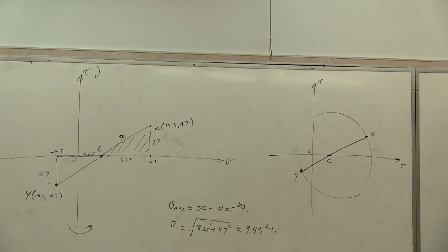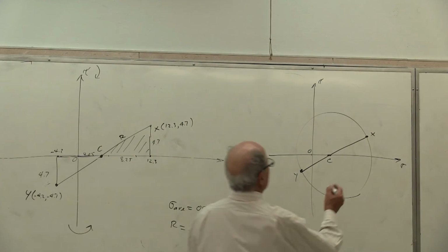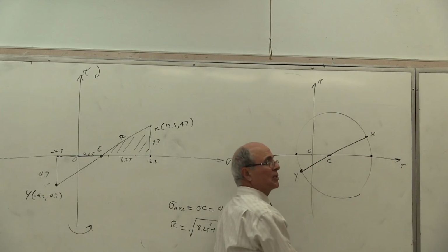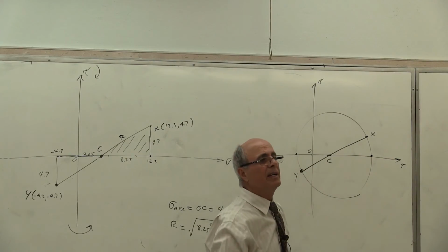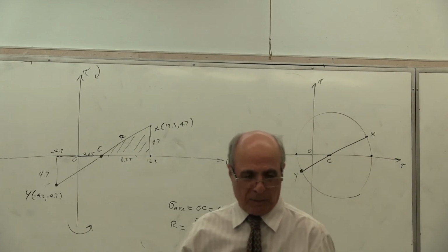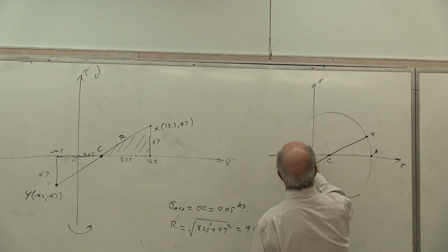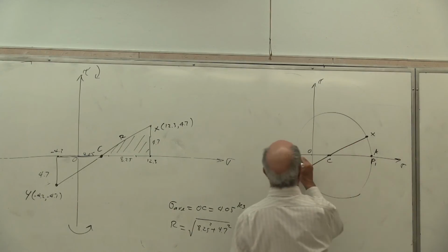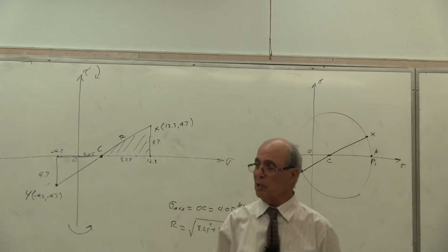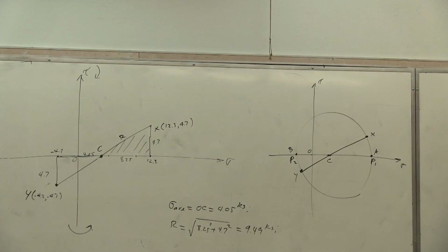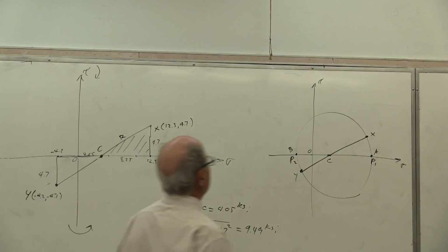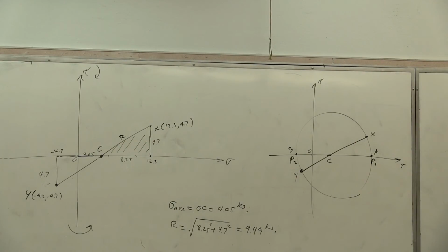Yes? Now, what happened here, I have these two. These two are called principal stresses because this is the largest and this is the minimum. So those become an essential part of your design. So this I usually call A and call B. We can call it principal 1 and principal 2. Please call it like that because in the next handout that I give you, they are represented not with A and B. They are represented with principal 1 and principal 2. Everybody understand that?